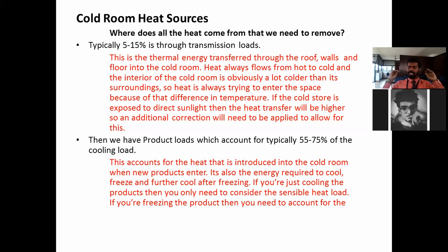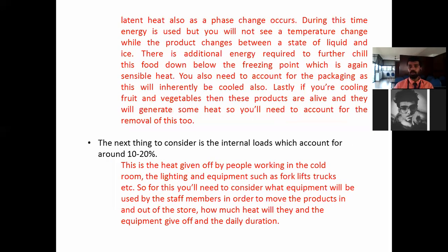So when you are deciding only to cool something, we just need to consider only the sensible heat load. If you are freezing the product, then you need to account for the latent heat also, because there is a phase change. Understood what I'm saying?